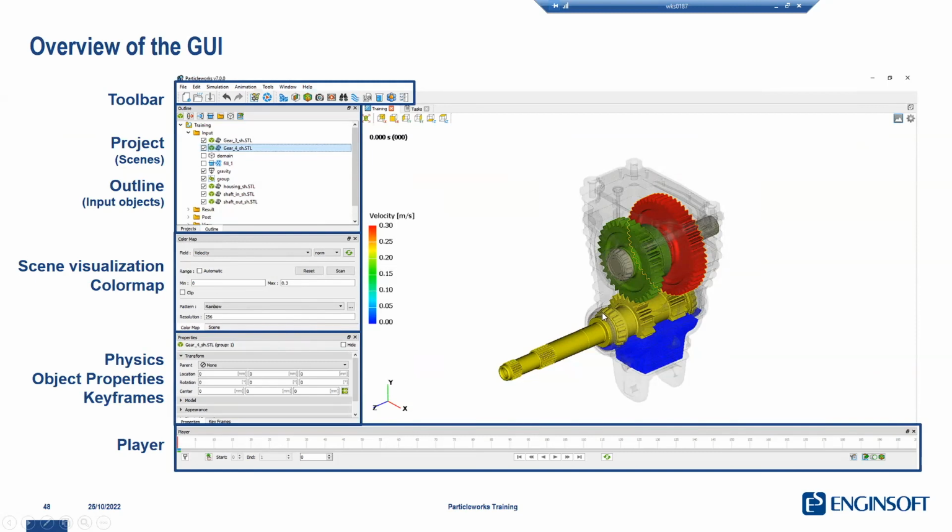Just a quick question on the tool again, just again from a layman perspective. How is the simulation of the rotation of these gears and how they interact with one another? What I was following earlier was the simulation is performed on the particles that are around the gears. Is the tool also simulating how the gears interact with one another? Sure. So here we don't have a play button, but we would see this rotating, the fluid lifted up. So the position is controlled by us. So we are not modeling the solid-to-solid interaction, nor are we modeling, for instance, the friction there. Okay, that is imposed by the user.